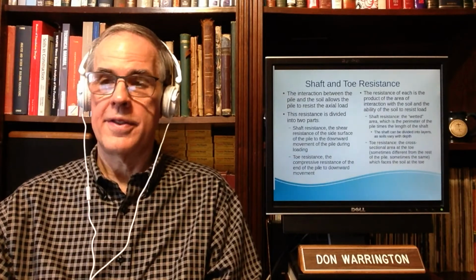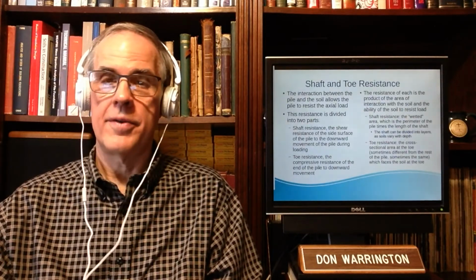So that's my way of illustrating it. The total resistance of a pile is equal to its total shaft resistance, which is a force, plus the total toe resistance or point resistance, which is also a force.